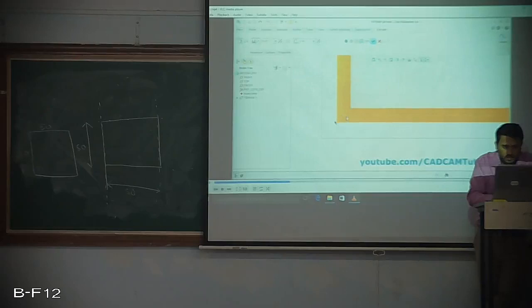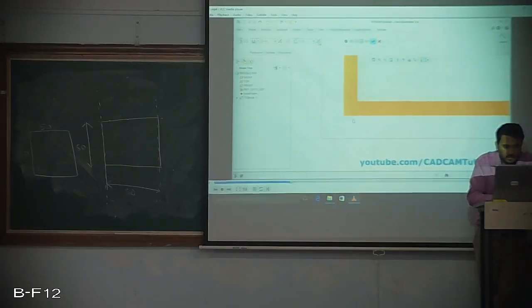This is the sketch. Initially, if I have changed the thickness with respect to the sketch, outside it has taken 1 mm and inside it has taken 1 mm. So together the shell thickness is 2 mm. If I click it one more time, you can see what happens.